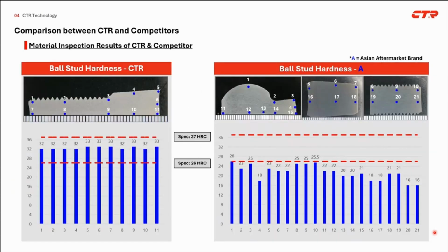It shows the detailed result of the hardness measurement at the center and near the surface of the bolt. In case of the hardness, we checked whether products meet the general hardness specification, which is a common automaker requirement, or not. Because if the hardness is higher than the specification, there is a risk of cracking when the screw is tightened.